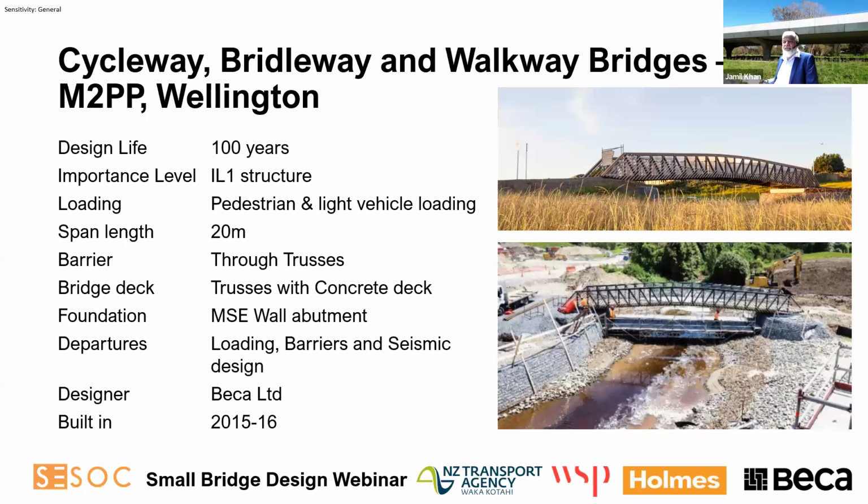We applied departures for the loading, barriers and seismic, and this is one example. This structure was not designed for any seismic, and there was an area of liquefaction. The understanding with the client was that if an earthquake liquefaction happens, the bridge will move, and they can reinstate it, as it's not a critical access required during the earthquake, and then they can bring the bridge back post-earthquake. It was designed by Beca and built in 2015 and 16.